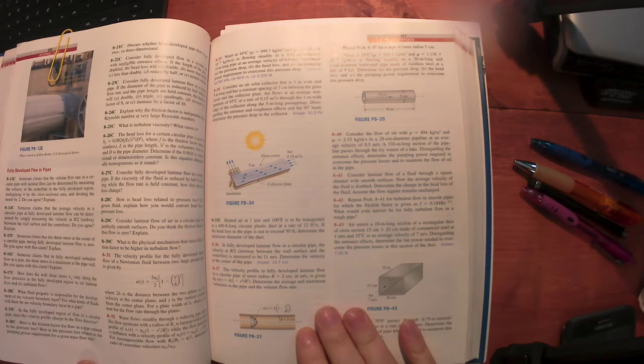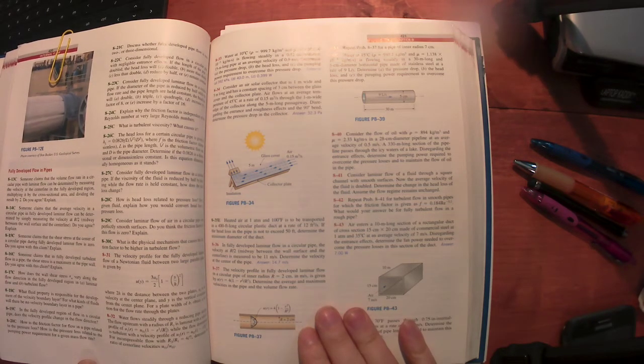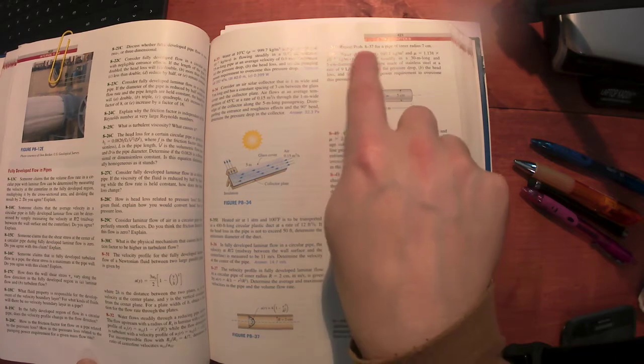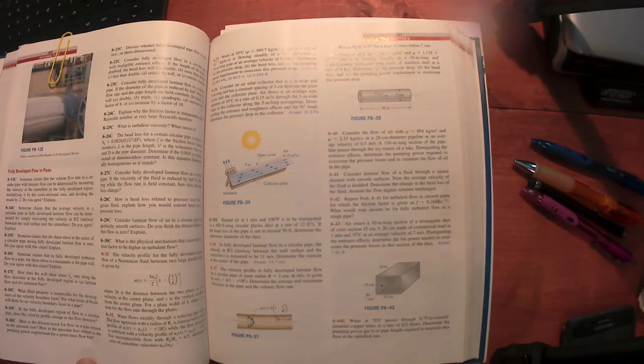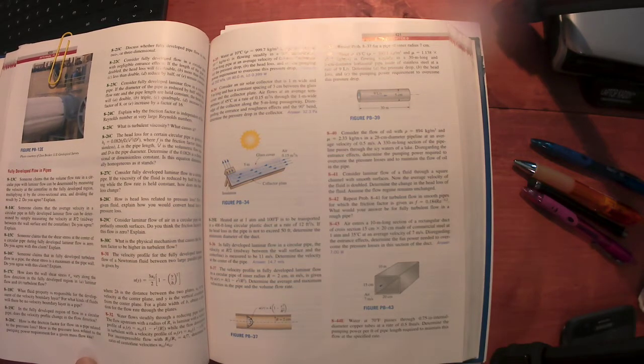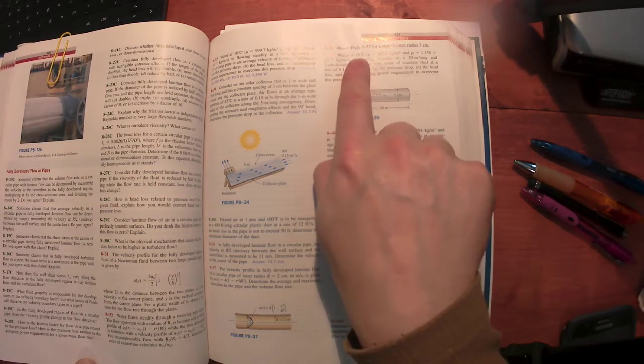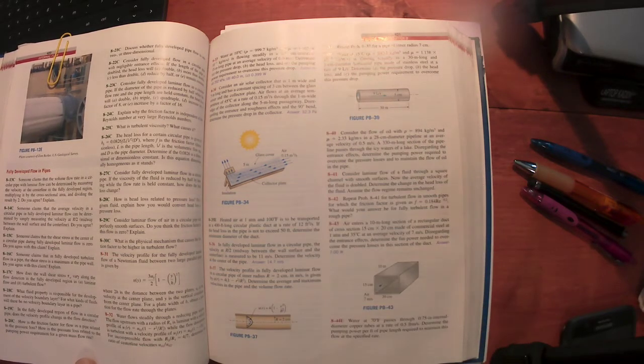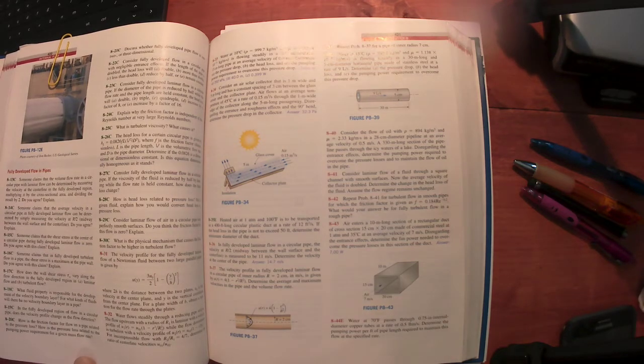The density of liquid water is reasonably constant, but it will vary some with temperature. Viscosity will vary significantly with temperature. If these numbers are not given in the problem statement, we can go to the property tables in the back of our text and look them up. Given the temperature, saturated liquid water will have essentially the same properties as liquid water at that temperature.